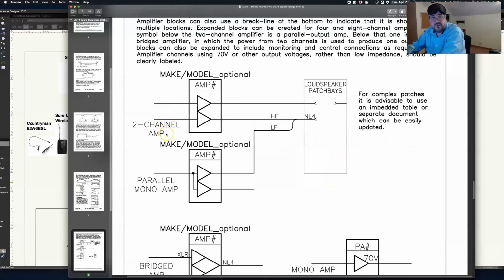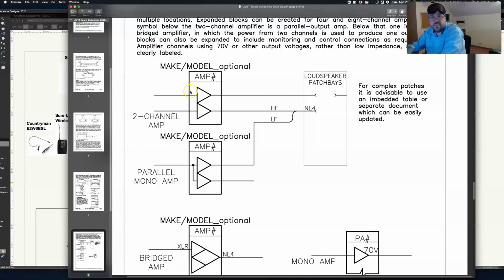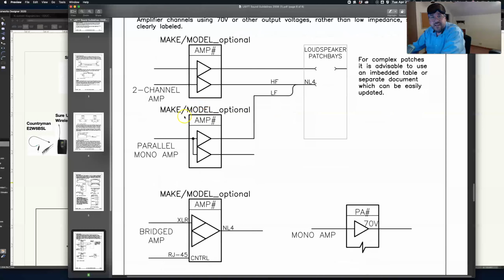First, parallel mode. Okay. I'm sorry, in 2-channel mode. That's where one comes in, one goes out another, comes in one, goes out another, and the triangles represent the amplifiers. It's the same sort of device box, but with triangles in there. Now, if it's in parallel mode or mono mode, then you're going to have them bridged together or put together like this. Now, bridged is the wrong word, because you're going to have 1 signal in and 2 signals out.